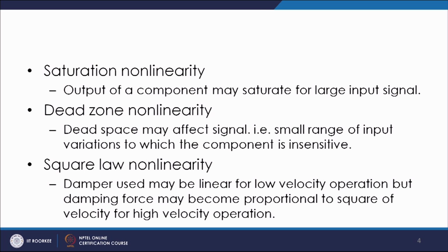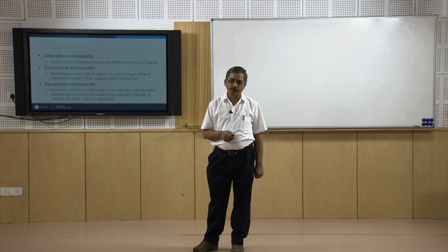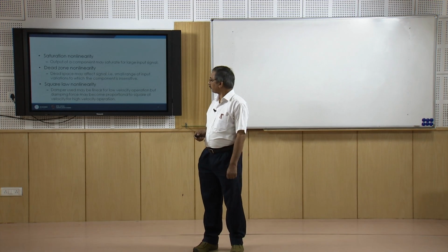Then the dead zone non-linearity: dead space may affect signals, that is, for a small range of input variations the component becomes insensitive and you do not have any output from it.